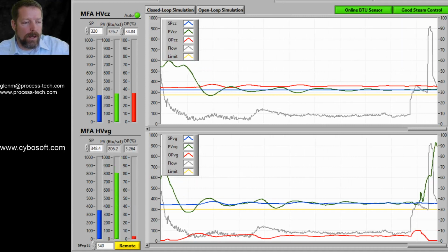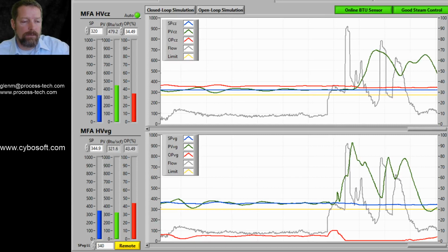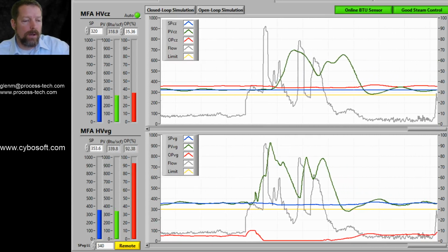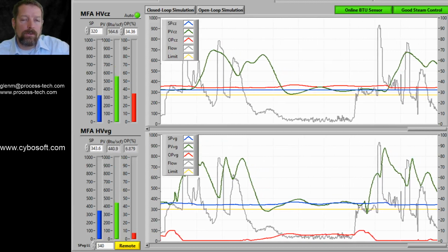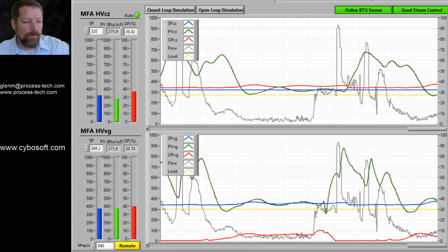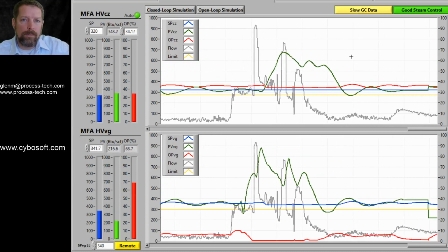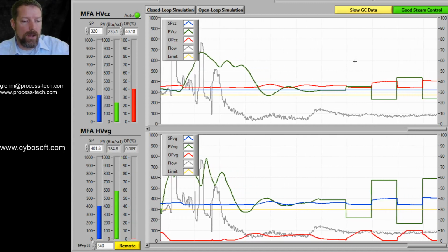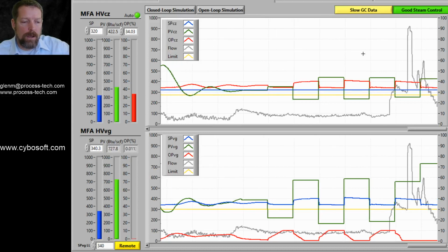We're going to simulate what would happen if you relied on your gas chromatograph to determine net heating value here. But in this simulation, the output value that would control your fuel gas and steam assist, if you're using a steam assisted flare, is represented in red. Let's just flip this switch real quickly, show you what happens if you use a gas chromatograph, as many of our customers invested in GCs for subpart JA compliance in 2015 for reporting to speciate.